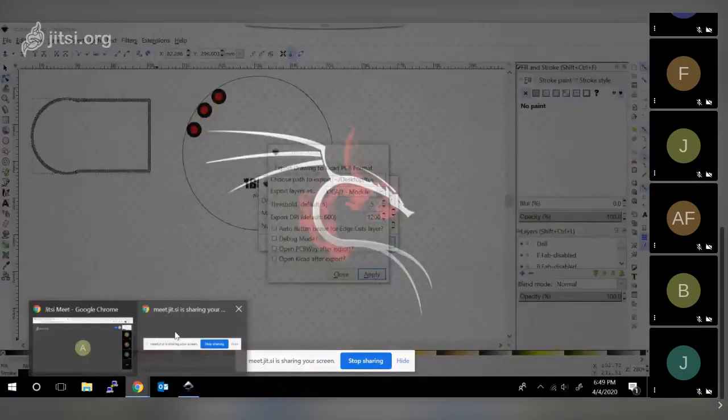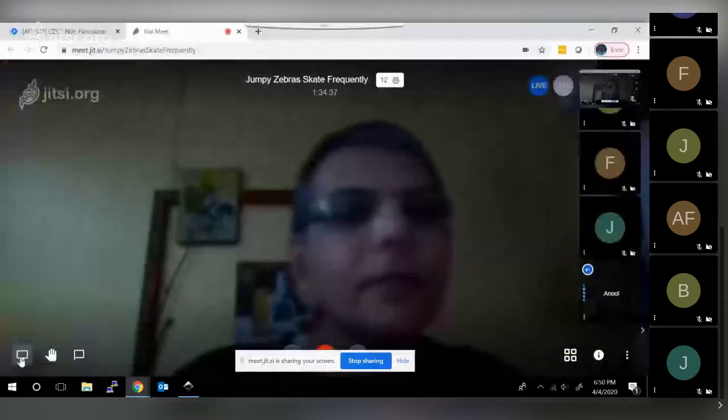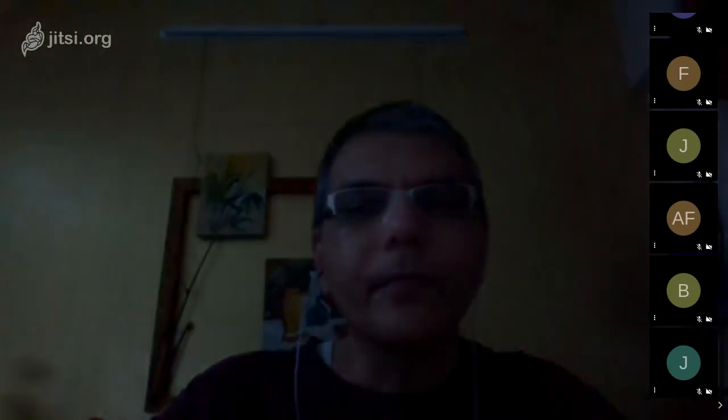Oh, that's super cool. Nice to know that. How do you decide what DPI to use? The higher the DPI, the better the resolution your PCB will get. So 600 is the minimum for a lot of the board houses, but I have gotten really good results going to 1200. If you are using true SVGs, then going to 1200 will not be an issue, and you'll get better results.